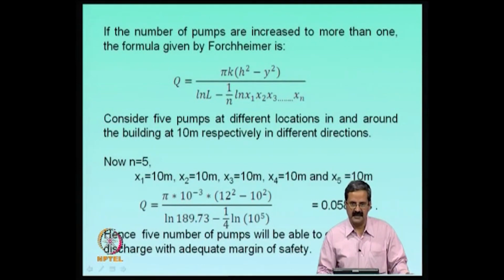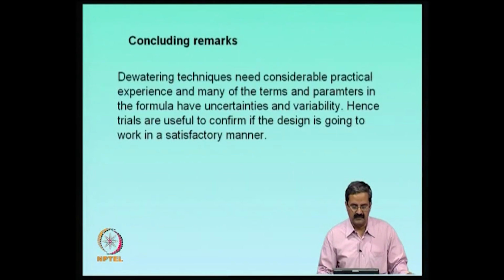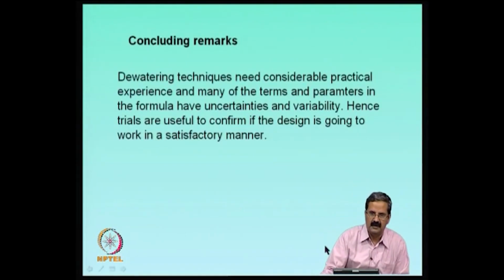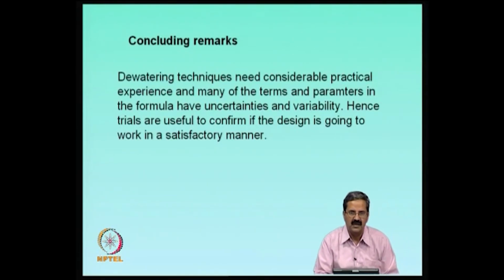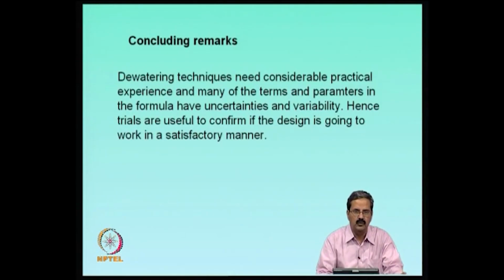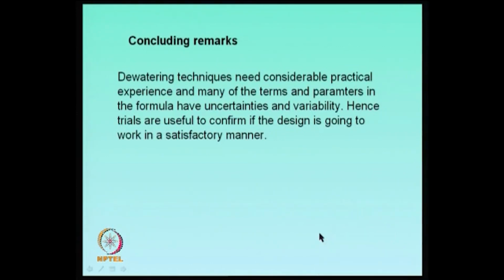So, this simple example illustrates that one can do a design of the dewatering system in a simple way. Of course, in this issue one should understand that the use of dewatering techniques needs considerable experience. It is not easy; you have specialized contractors who will have an array of systems, and if one goes wrong they can use something else. If dewatering goes wrong, it is very risky in foundations, and a lot of problems will come up all of a sudden.